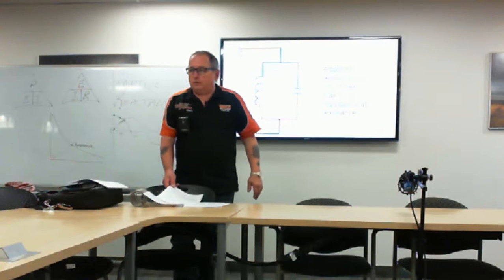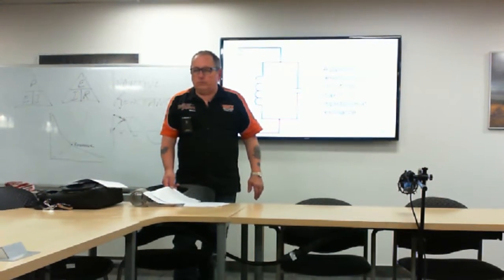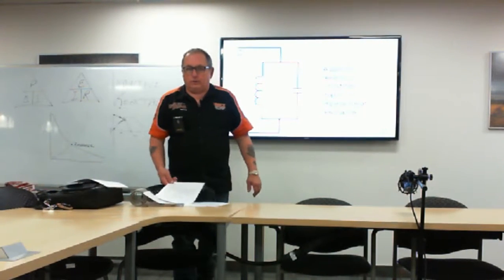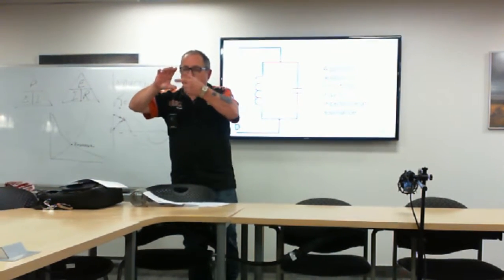So is that kind of like a relay switch, where all of a sudden it kicks on? No, that's a solenoid, and a solenoid is just an electromagnet. A solenoid is slow at the start, but as the armature gets into the coil, it picks up speed because the magnetic field becomes stronger.